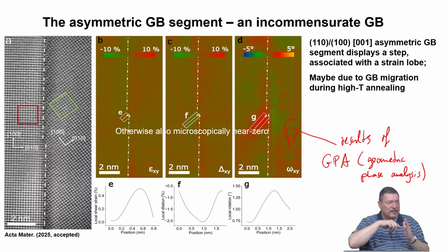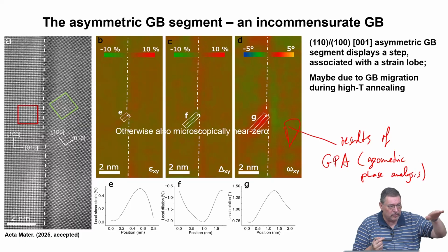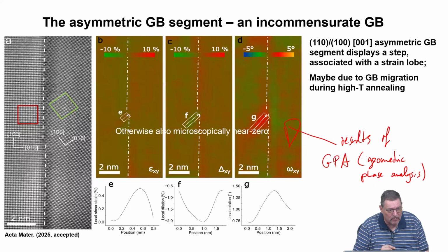So it calculates the Fourier components of the intensity distribution in Fourier space, then does the retransformation into real space, and you get these spatial color maps or heat maps, which are shown here, which show you, for a given component of the in-plane strain tensor of the TEM sample, the distribution in space of these components. So color change means strain state change.